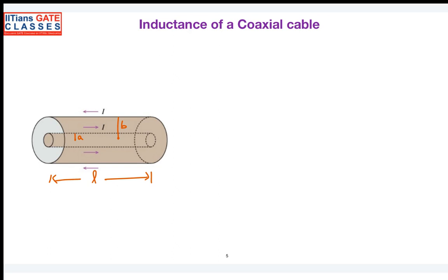Do you remember what I said? When you consider a coaxial cable, do you have any magnetic field? We do not have anything outside the cable. The magnetic field is there. Where is the magnetic field present in that case? It is between the inner and outer. What about when it is inside the inner conductor? Zero, sir, because no current is enclosed in it.